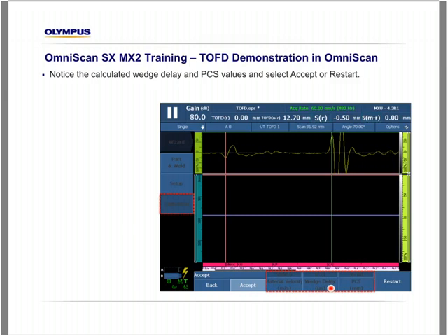And now we see a new PCS. The operator attempted to set the PCS as close as possible to his desired focal point, but with a known calibration standard, the software knows the real PCS. And as long as it's within a couple millimeters of where you want it to be, it's more important that the software knows the real value. That PCS now is a constant for future calculations.